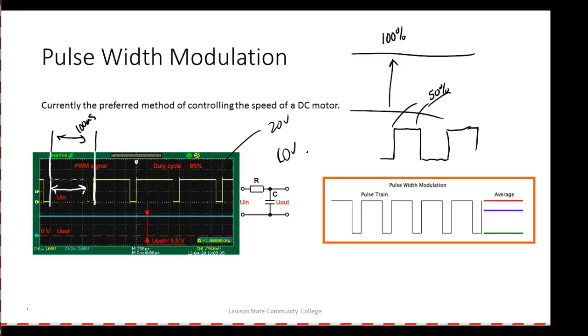So what I'm going to do is come up here and take my function generator. This function generator has the ability to generate pulse width modulation, because we can do it electronically, right? You understand that? I'm going to hook up my oscilloscope to this. And of course, I'll probably get a DC meter. It'll actually show you as the pulse width goes up, the DC voltage goes what? Up.